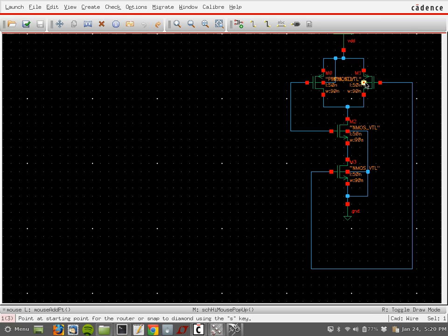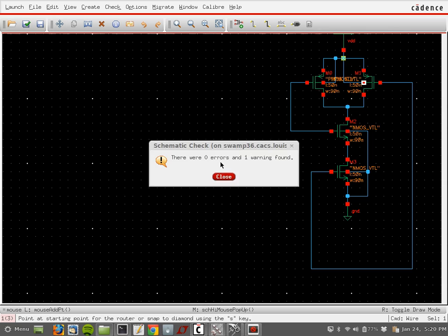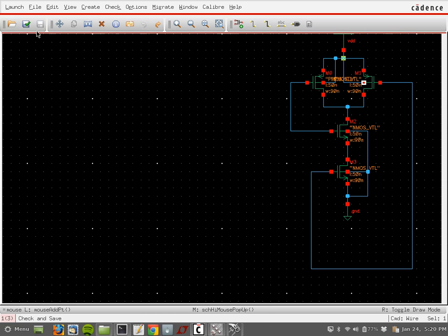And by the way, there's something very annoying about Cadence. I don't know if they did it on purpose or what, but if I try to connect this on this dot, if I try to connect it here, it will display an error. It doesn't like 4 wires connected on one dot. You can at most connect 3 wires to one dot. So if I have to connect it, let me delete it.